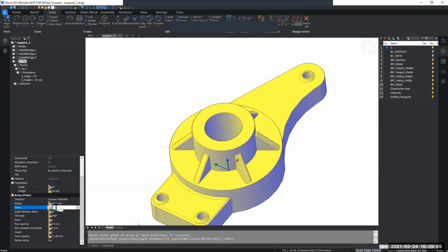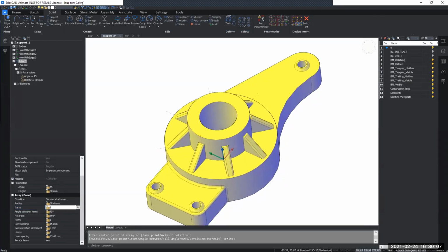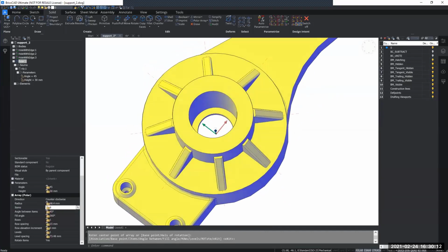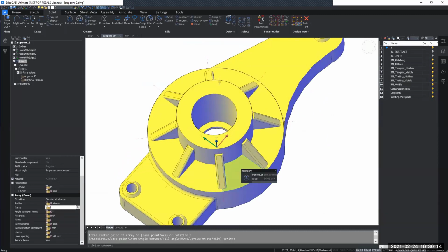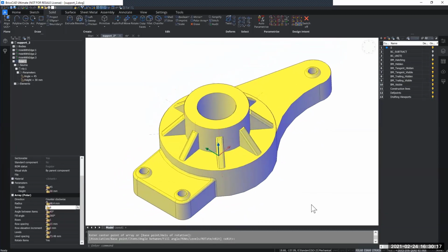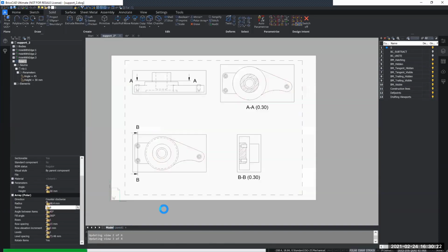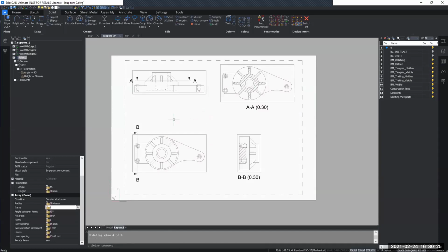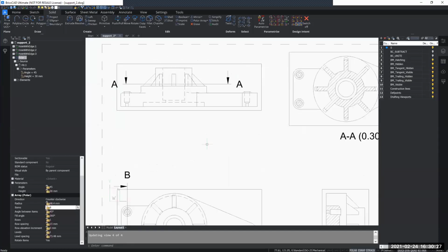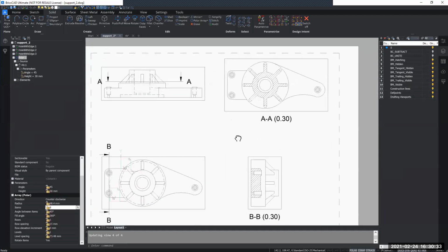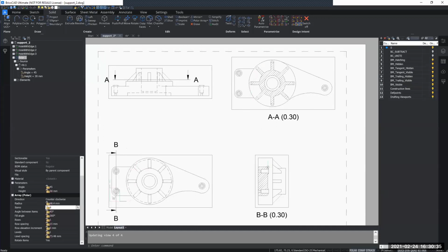If I want to add more items, I can change the value of 6 to 8, as it says in the handout. And you can see in the model, it automatically updates to add more items. And it decides the distance between the different instances as well for me. Now I'm just going to the drawing view to check that everything is updated, and it is. I can see all the different ribs show up here in the base view, the projected view, and the section views.